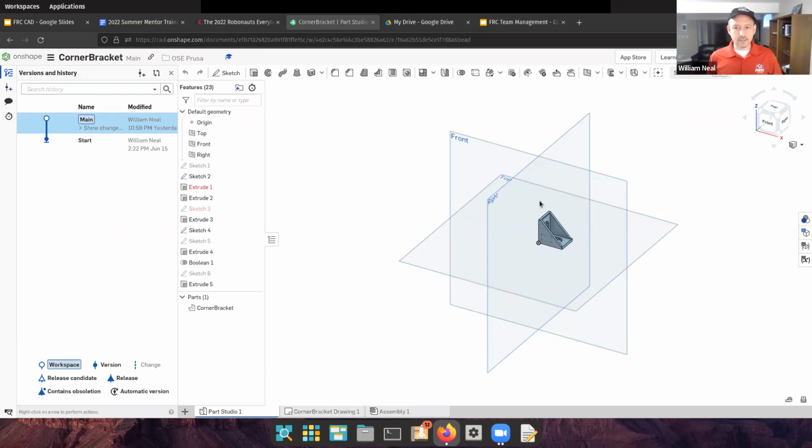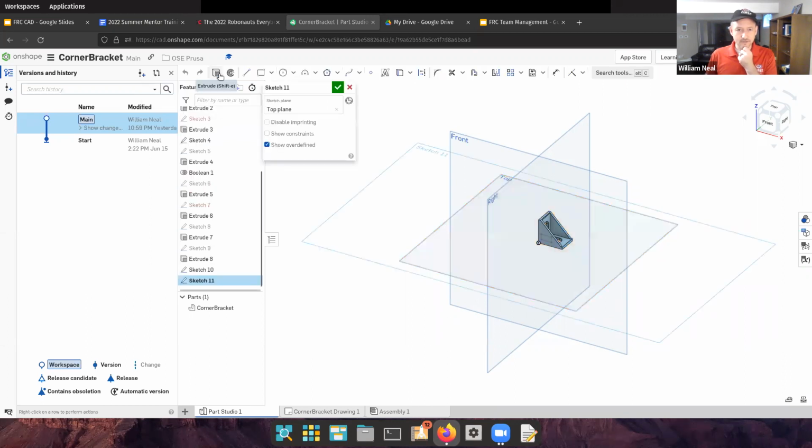So when I want to begin making a part like this, let's retrace the steps that I did to be able to do that. First of all, I selected a plane. I typically imagine the desktop, so I take the top plane, as it's called. And you see I just right-clicked it. And here we are, I've selected it. Now, if I want to do something like making a sketch, I can click that button, and I'm going to be able to create a sketch on that plane.